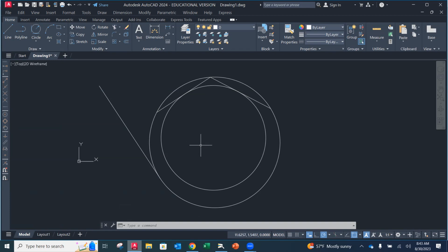Another command that's really handy is called a fillet. A fillet essentially is a tangent radius. It actually is, if you construct it, but it's a shortcut. So I'm going to first create 2 lines, and I'm just going to make them perpendicular. I'm going to have a sharp corner, but it can be whatever. It's just a random corner that I created.